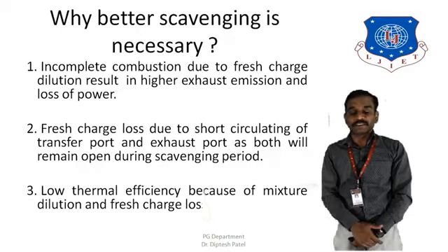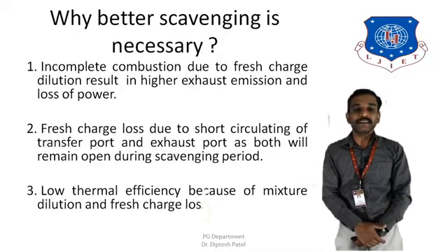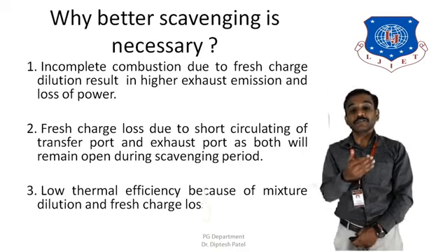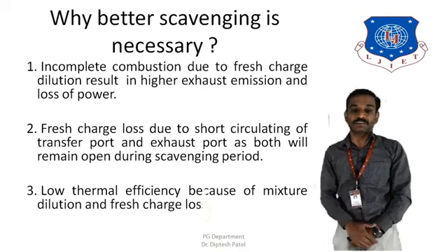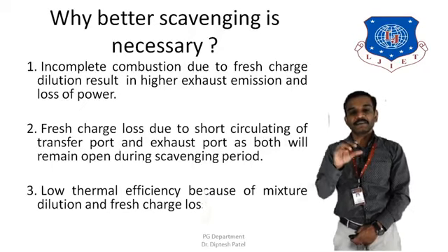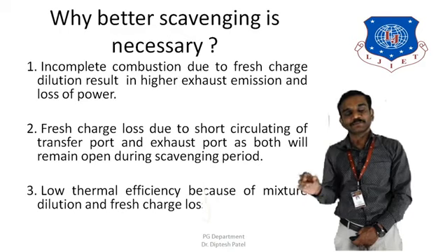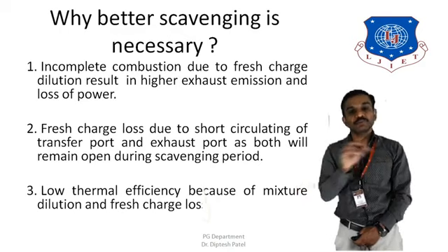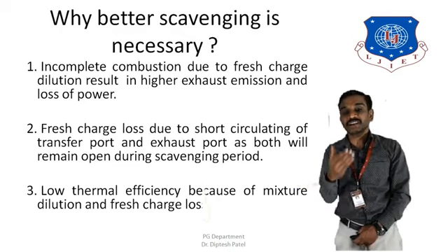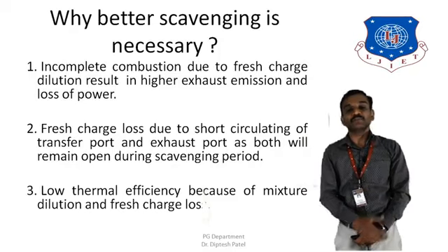If the scavenging process cannot be completed properly, there may be a chance of losing the fresh charge along with the gases through the exhaust port. This especially happens in a two stroke engine, because for a certain period of time both the transfer port and the exhaust port remain open, and there may be a chance that the fresh charge coming in from the transfer port leaves through the exhaust port.